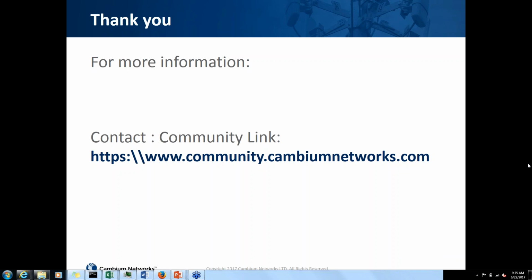So the main benefit of HCMP compared to a traditional point-to-multipoint system is that HCMP is designed to be multiple point-to-point links. So we are not looking to have a large number of subscribers, like the few tens or hundreds in our 450 portfolio, for instance. In that case, we're trying to have a small number, up to 8 links, which have the same characteristics as the PTP links. So we divide the bandwidth between 8, but we try to keep the low latency and a dedicated throughput for each of the links.